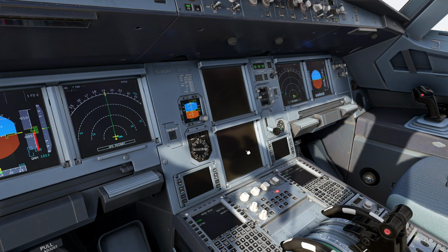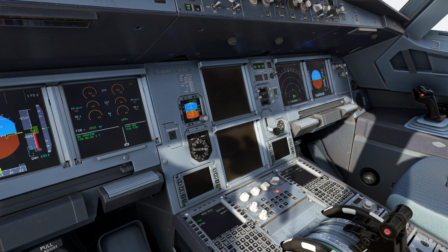As I mentioned, engine warning display has priority over system display. I selected the engine warning display through the ECAM ND transfer switch to the captain side, and you see the ND or navigation display replaced by engine warning display on the left side.